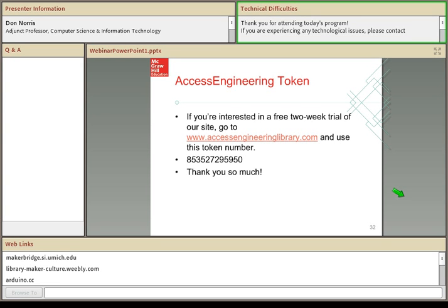In fact, I know you can. You can use what they call a piezoelectric strain gauge for certain. So there might be a little bit of interfacing involved, but you definitely can do that. And unfortunately, the Arduino needs an analog to digital converter, so that would have to be factored into it.